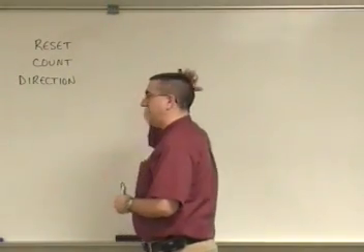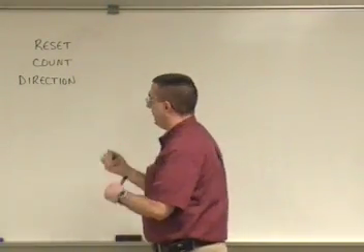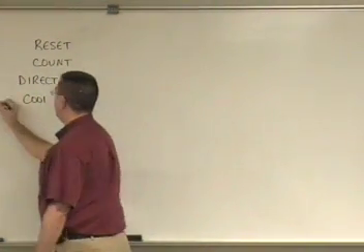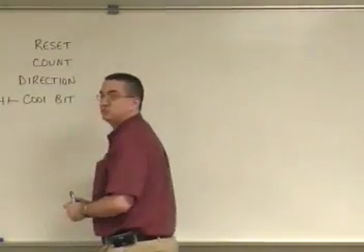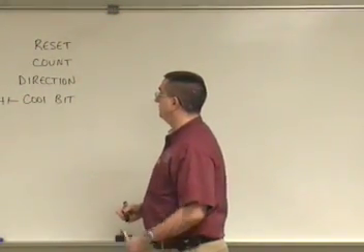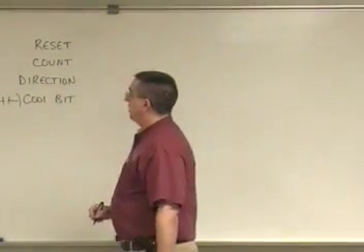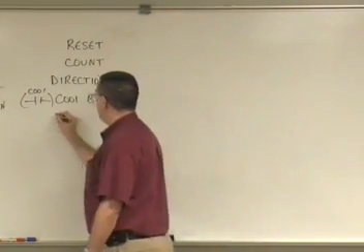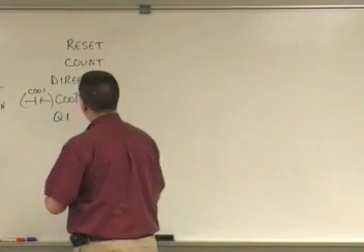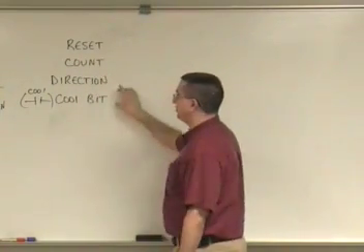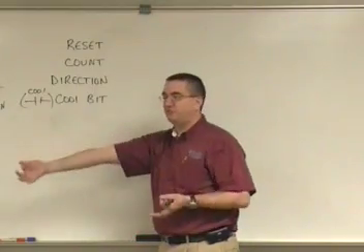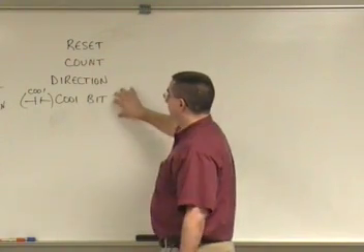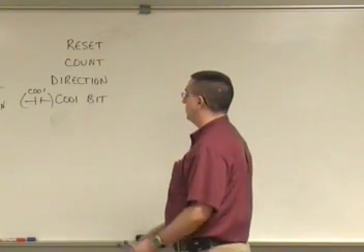And then let's go ahead and talk about what we're going to energize. We'll say we had the C001 bit. And when I say bit, I'm talking about a normally open contact that's addressed to C001. Okay? That's what that means. And you could write that in there if you wanted to. The Q1, we don't even need to include the Q1 at this point. The C001 bit, anytime that's on, it would be energizing something, right? Could be energizing an output, could be energizing a timer, could be energizing anything. So we know that we can use that C001 bit. That's all I'm looking for there.